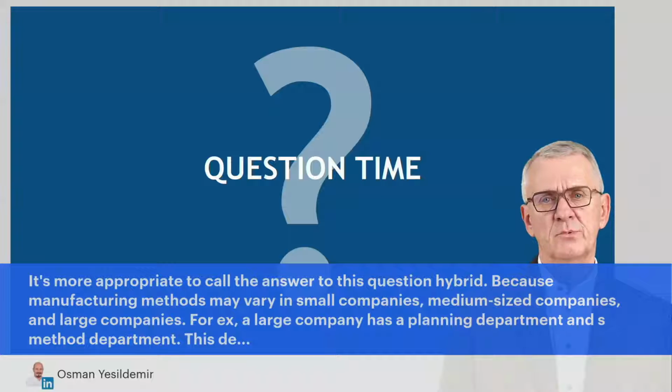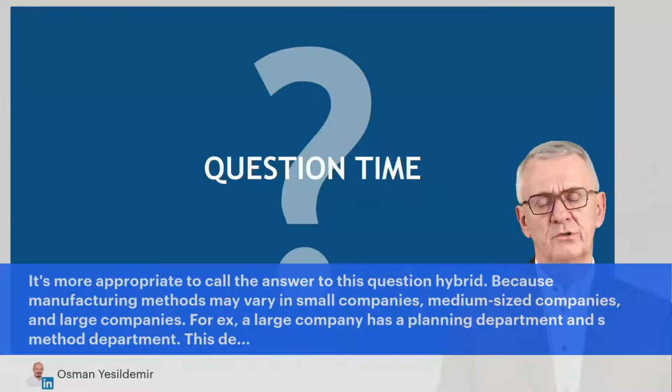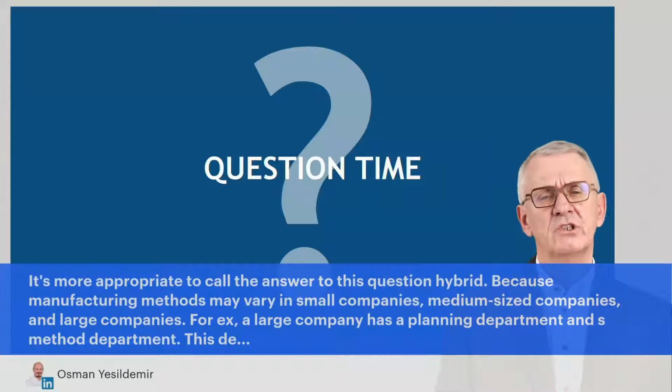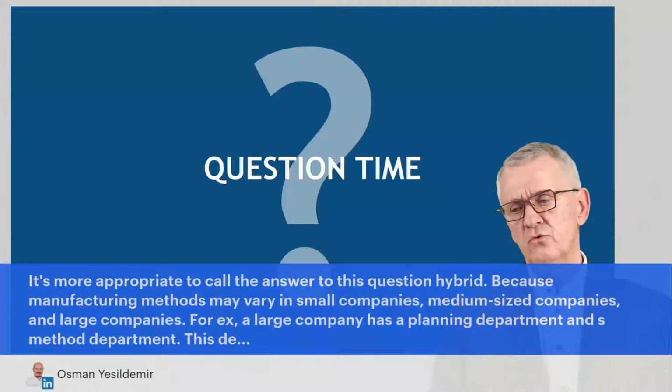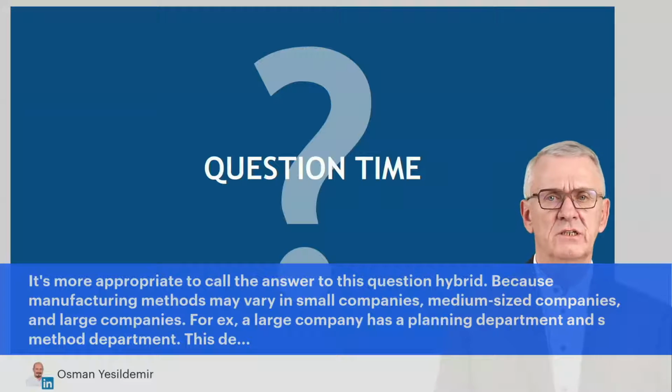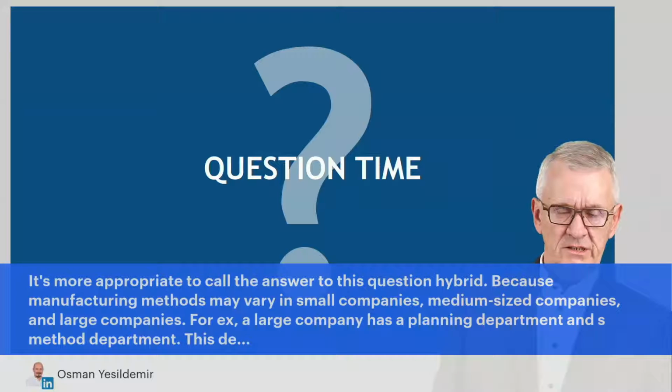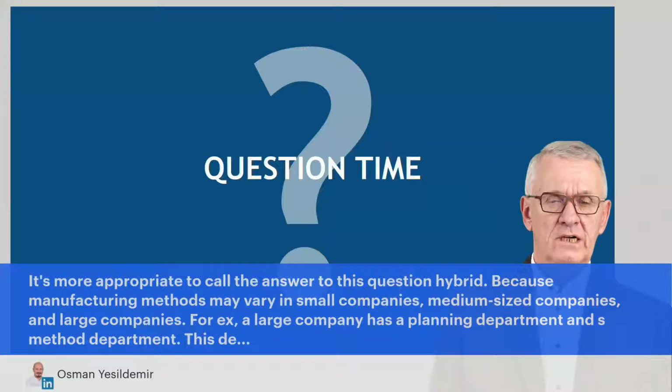And if we discuss productivity beyond pure machining productivity, but real production productivity, we have to be aware of that. And then indeed, as Osman says here, the way of working, how to select a tool, how to select cutting conditions, which tool path to generate, how to relate things to each other, will be influenced by the batch size. I fully agree with Osman that if you take one workpiece, and you say I have to produce 3 pieces of it, or you say I have to produce 3,000 pieces out of it, I also will come up with a different approach, very clearly.